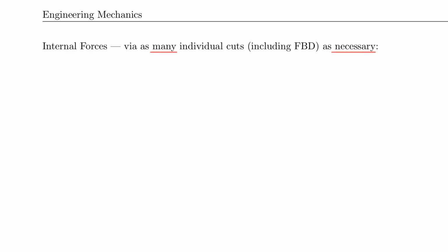So I will draw the free body diagram for cut A to B, which, if we remember that correctly, was just the left side of the system. So I have my free body diagram here, which how that works we really showed you in the previous lecture, but I cut it here at B, and I had support reactions which were 5 kilonewton pushing up here, and I had a 0 here, so I don't even worry about that.